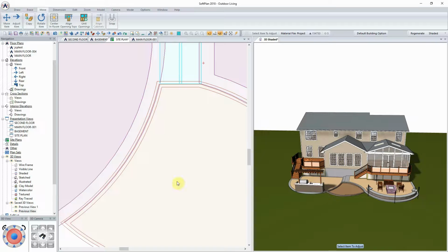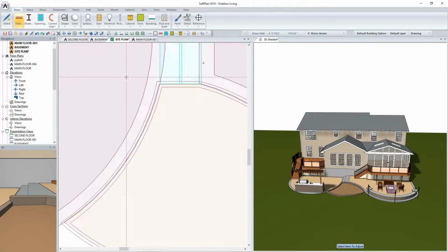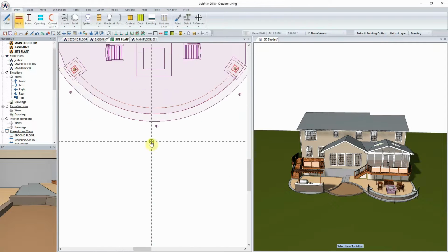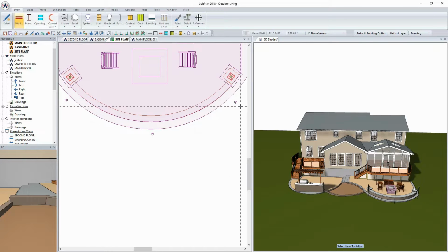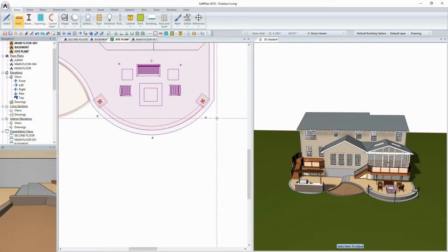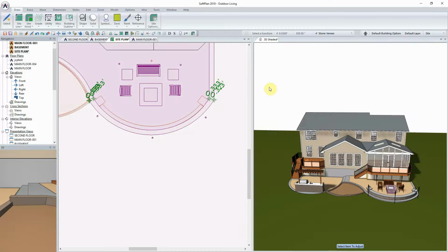So picking up at this stage now and zooming in here, inside the site plan mode, I'm just going to zoom this area up. And these little symbols here, if you'll recall in the previous chapter, were just little tiki torch lights that I threw in there. And I'm doing this again from within site mode. That's kind of the key here, just flipping back and forth between the modes of where information is going to be found. I'll pick the site work, and this time I'll pick the planting bed, and once again I'm going to select the line option.